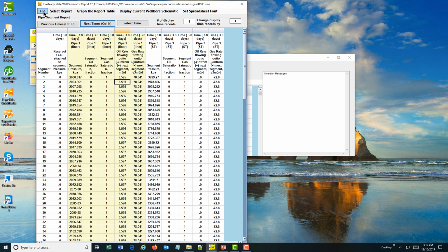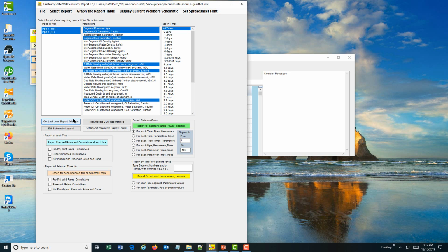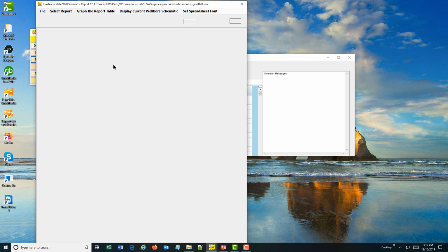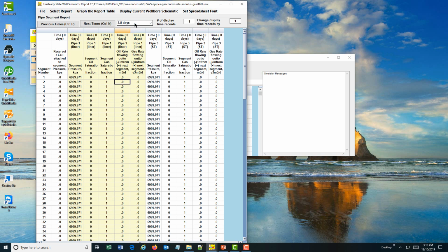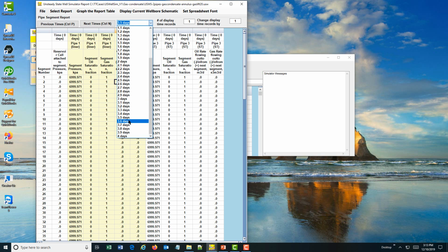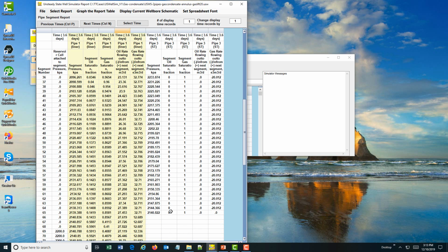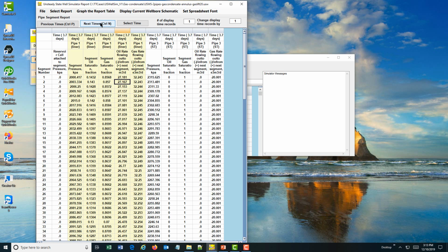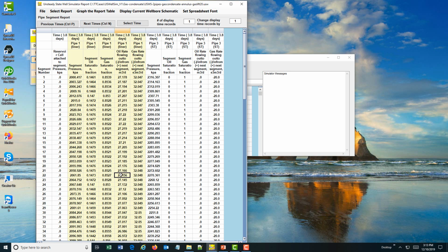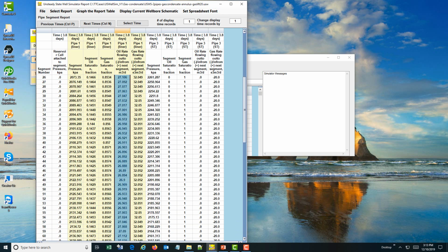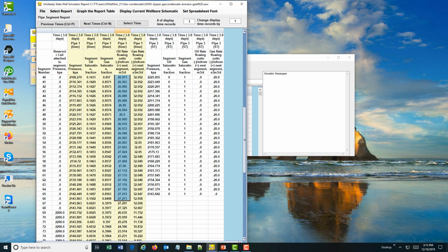So if we go to the results of the run of 20, and get the last used report selection and look at the time, about 3.5 days, 3.6 days. So at 3.6 days, we're injecting 20, so we made a target of 20. And going down, we can see it goes 20, and we're now producing 27 instead of 3 meter cubes per day of condensate. So 3.7 days, 3.8 days. So we're showing that we're getting better condensate recovery by injecting less lift gas.